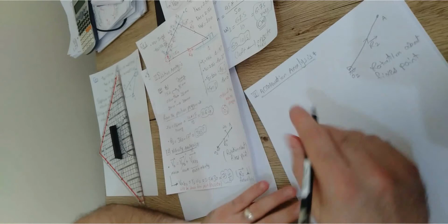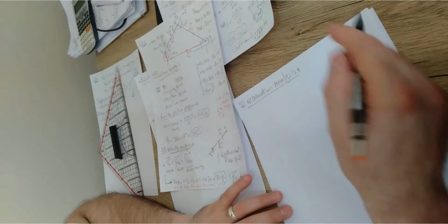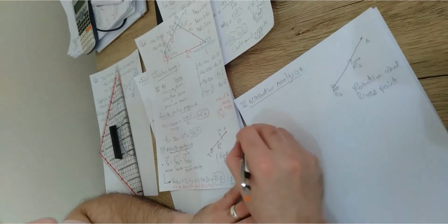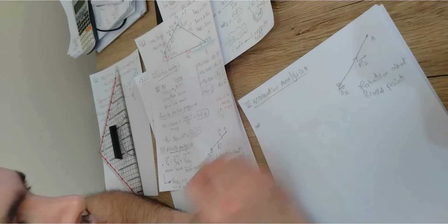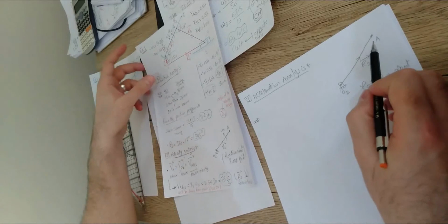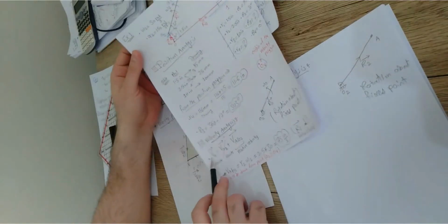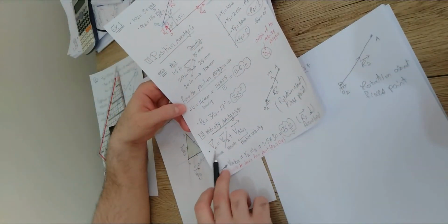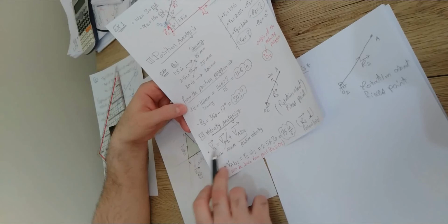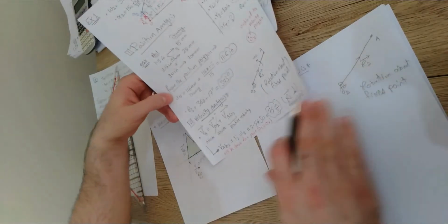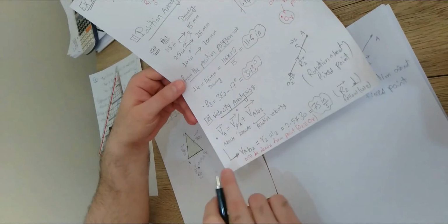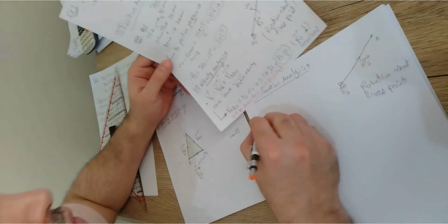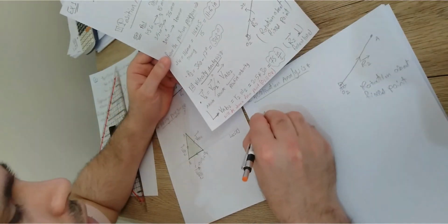So for this case, as you can see, the two points are point A and O2. Directly, the equation for this length: you can either start by defining VA, as we did for the velocity, writing VA on the left side, or VO2 on the left-hand side. The same thing applies for the acceleration. But try to stick to what you already did for the velocity analysis. I started with VA here, so it is better to start with AA as a vector.